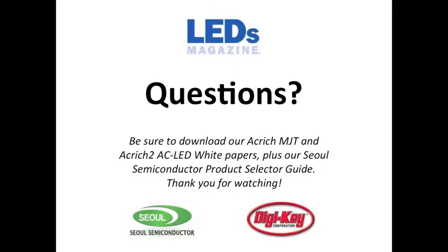I wouldn't say higher power is less reliable. It's just you're going to have a lot more heat created in that package. So if you're able to figure out a way to dissipate that heat, if you're running a 5-watt LED and you're running a 1-watt LED and that junction temperature is the same, you're still going to have a very reliable system. But if you can't get that heat out of that 5-watt package and that 1-watt is running a lower junction temperature, that 1-watt package is going to be more reliable. So it's really about getting the heat out of that LED.